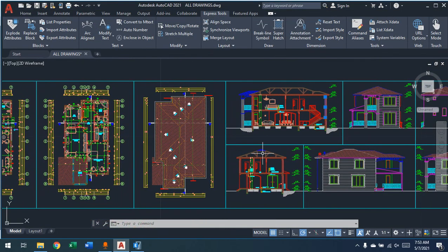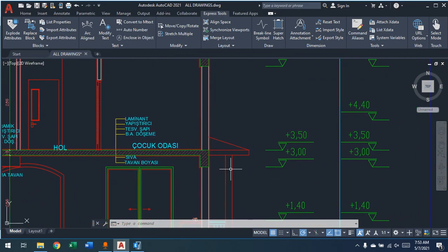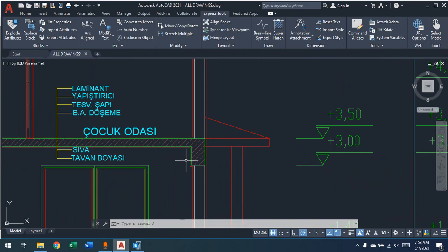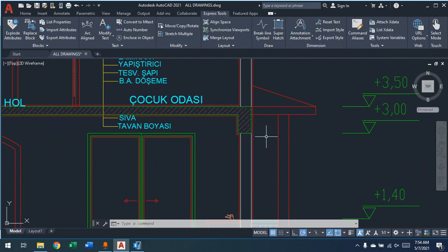So you only have this one. You don't know the size of the beam, but you will come up with something. It's already done here, for example, like they put something here. Yes, we can specify this one, use it there, and then let Etabs design. So the design process in Etabs, you can force Etabs to design the reinforcement based on the section size that you're providing, or you can provide multiple sections and let Etabs choose between the sections that are appropriate for the location.